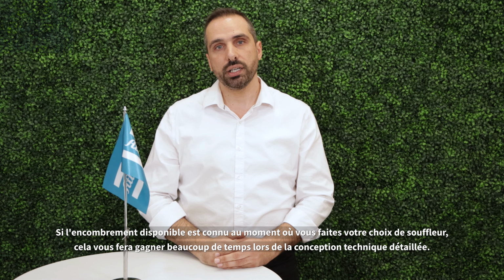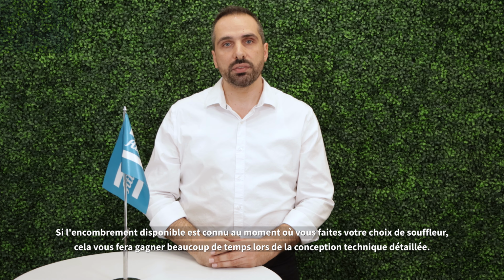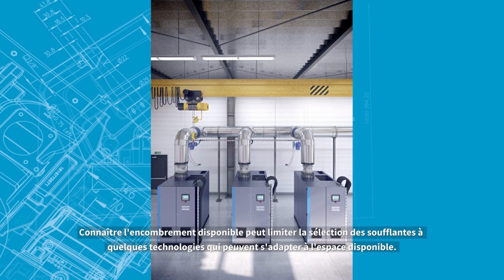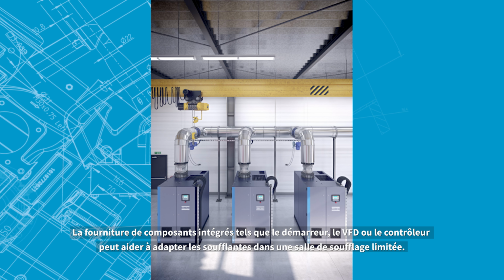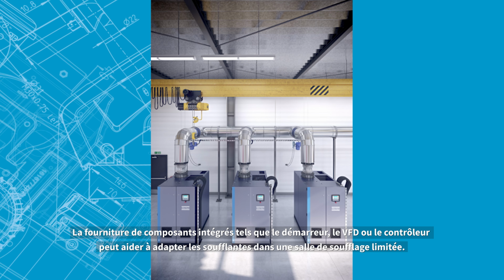The fifth criteria is footprint, the available space. If available footprint is known at the time you are making a blower selection, it would save a lot of time during the detailed engineering design. Knowing the available footprint may limit the blower selection to a few technologies that can fit the available space. Providing integrated components like starter, VFD, or controller can also help fitting blowers within a limited blower room.